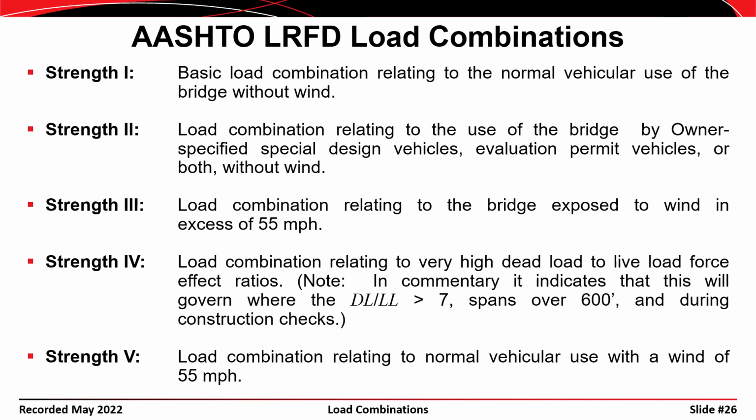Okay, so the bottom line is, for components not typically governed by wind, strength 3 and strength 5 don't need to be checked. And strength 1 is typically the one that governs.